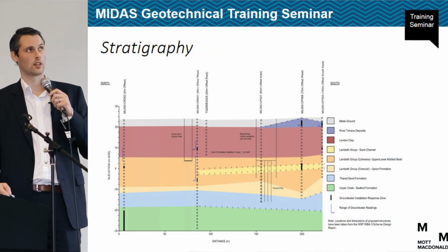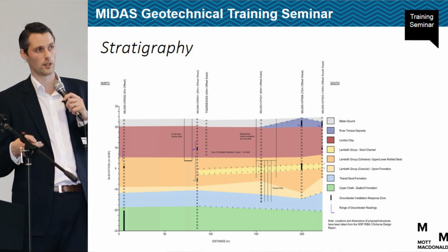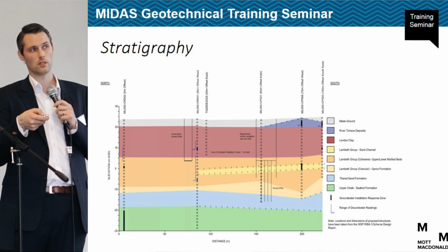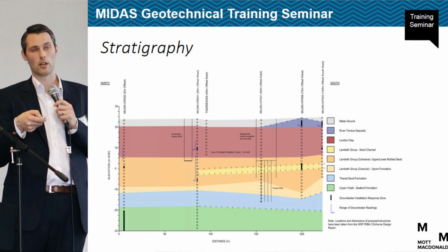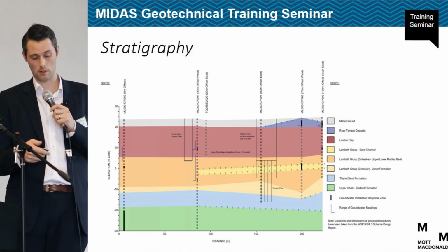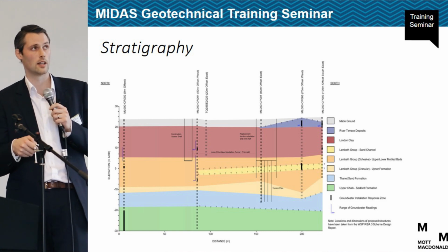We've already seen London stratigraphy today, so we don't need to go over that. The only point of interest for this project is this potential sand channel somewhere near to the formation level that may or may not be water bearing. So that's something we're going to have to consider in our design and analysis.